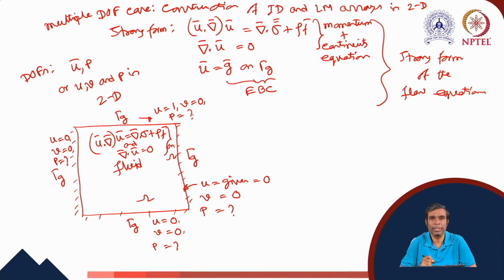So all the 4 boundaries are rigid boundaries. These are the no-slip boundaries. At a no-slip boundary, we have no-slip conditions for velocity and temperature. We are considering an isothermal flow problem, so it is only for the velocity. There is no slip condition for pressure, and at the wall, pressure is never a known quantity. Pressure has to be determined from the Navier-Stokes equations of motion. It means that for this particular set of boundary conditions, pressure acts as an unknown within omega and also along the boundary. So this is the physical problem which we have identified with respect to the boundary conditions and governing equations.